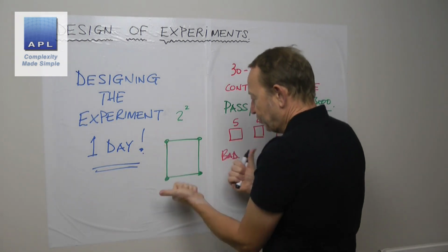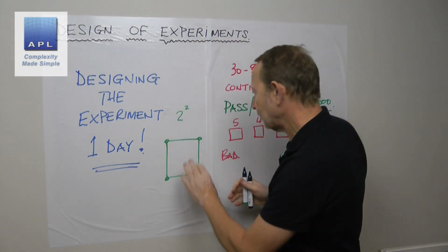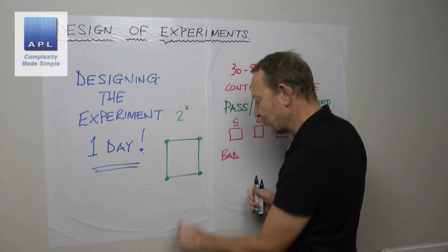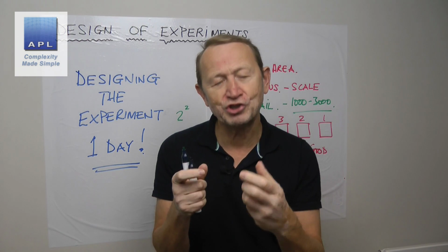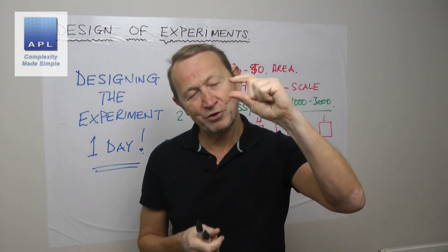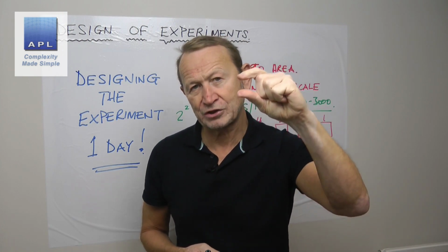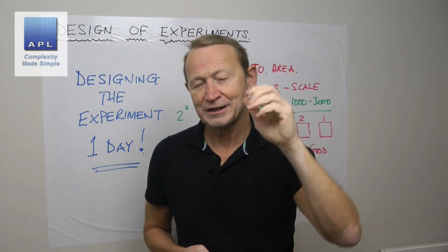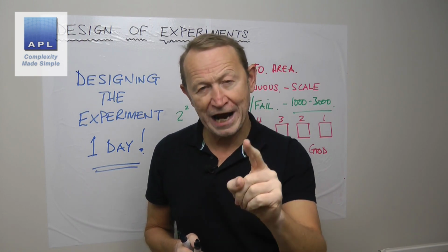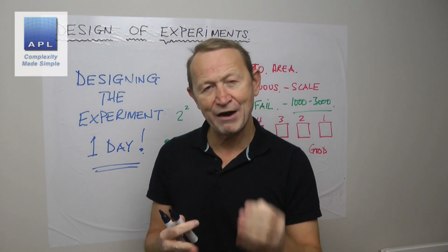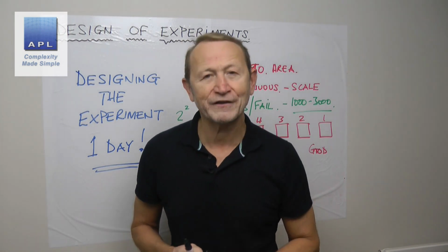And what we want you to do is get the box nice and big to put a signal through the data. Obviously, if you do that, you bump the results into extremes. Now, if you've made a jig for manufacturing, of course, the jig for manufacturing just wants to measure within the little window where the tolerance is. But maybe you're going to make these results go outside that window. So will your measurement system measure the extremes? Check it. We want to make sure there's no errors in this experiment. It goes off perfectly. So check the extremes.